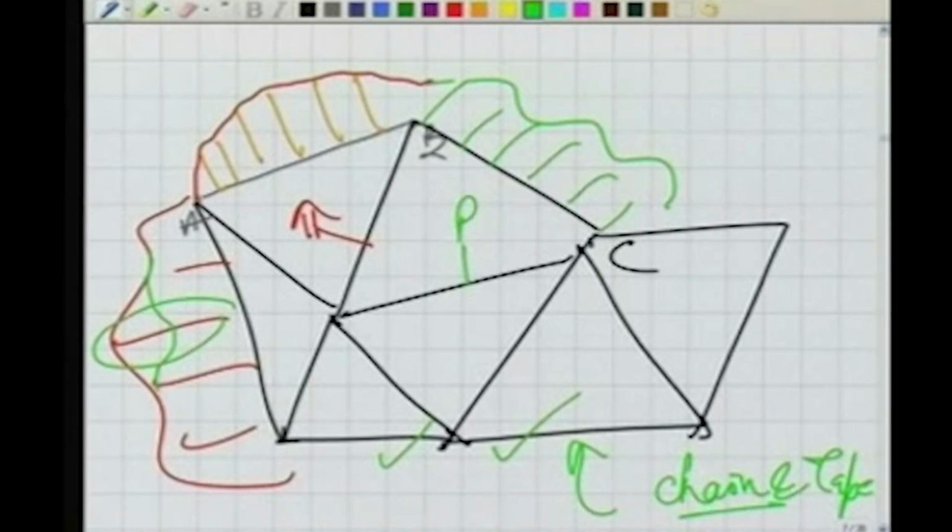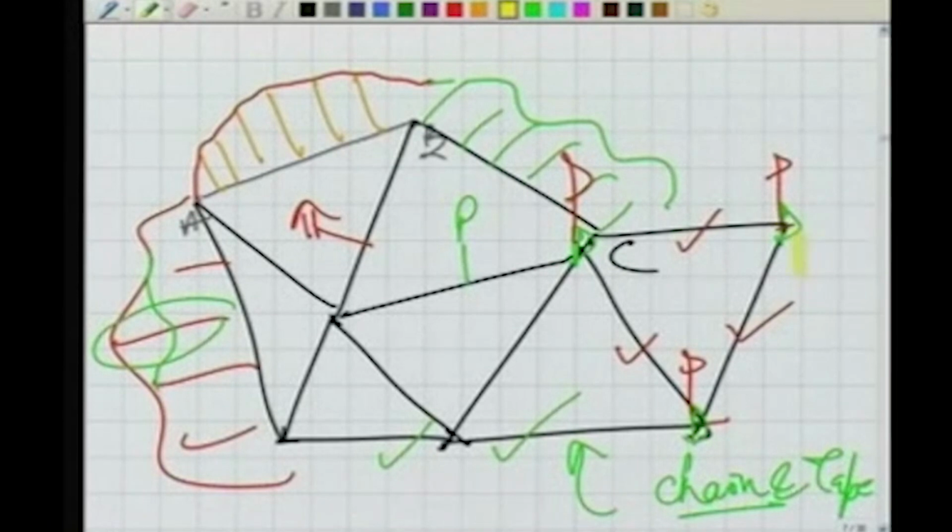What you are doing there, you are establishing some stations, and you have the ranging rods there, one ranging rod, another one, and everywhere you are measuring these distances. These distances can be measured using the chain or tape. So we are not carrying out any extra measurements, only the linear measurements. So using chain and tape, we can do triangulation, we can plot the things.